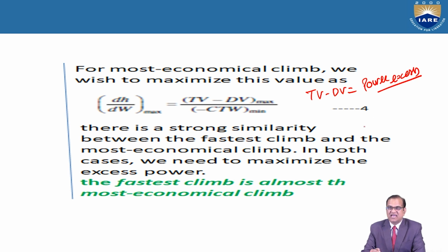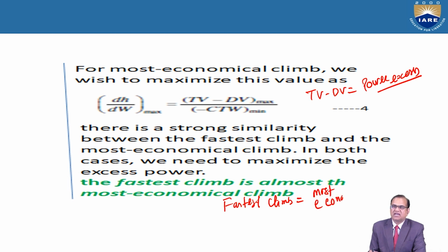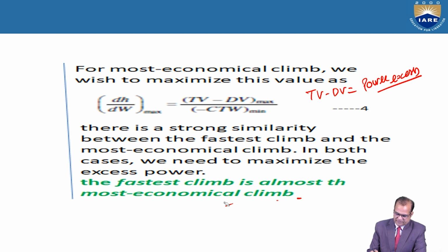For the fastest climb also we need the highest excess power. The fastest climb is almost the most economical climb. So if you are flying with the fastest climb, it is also equal to the most economical climb. Both are the same. This we have to take care of.